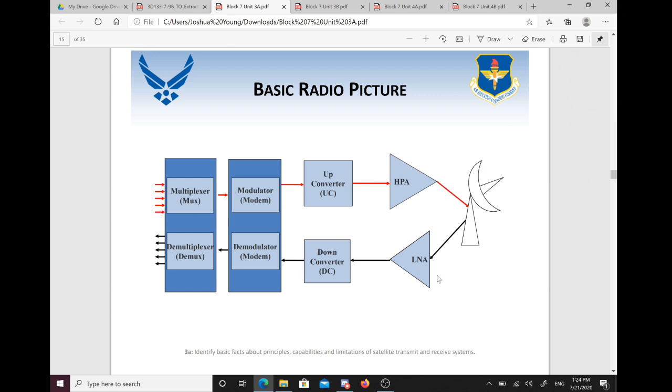And then on your distant end, after the signal is sent out of your antenna, your LNA will then pick out that specific RF frequency amongst all the noise and distortion, amplify it, and transmit it to your down converter. Your down converter takes the incoming RF, strips the local oscillator frequency that is resonating inside of it to generate a 70 or 700 megahertz IF out, depending on whatever your equipment is designated to generate.